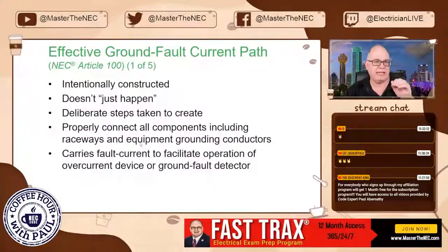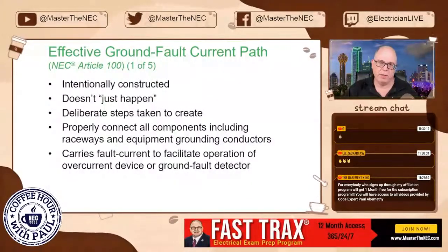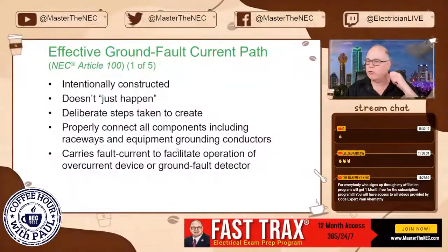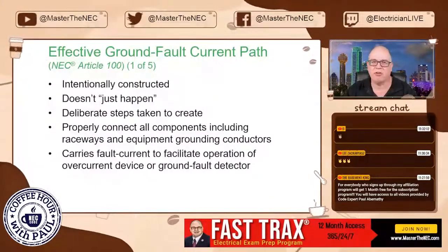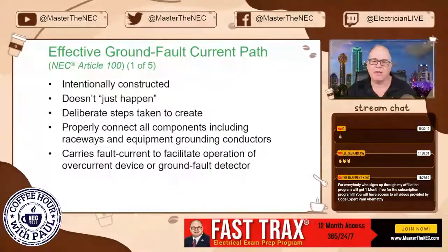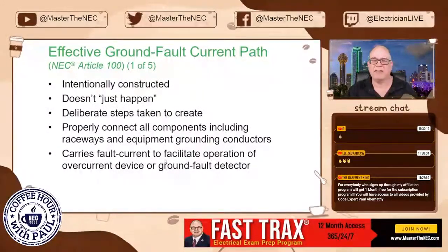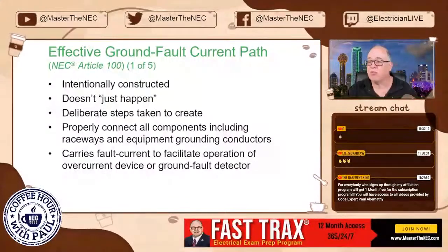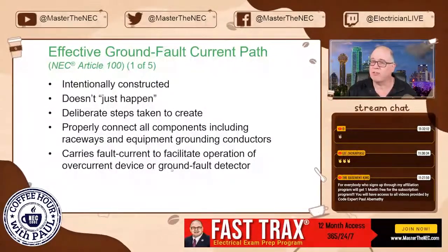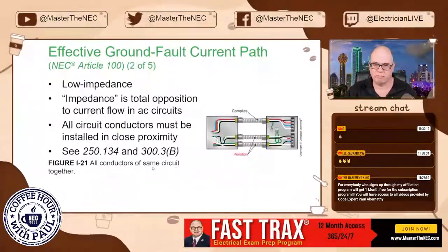You need to habitually train your folks on that. Properly connect all those components, whether it's the raceway, the fittings, the terminations, connection to cabinets, all of that. It carries fault current, again, to facilitate the operation of the overcurrent device, as well as, in some cases, for ungrounded systems, ground fault detectors, okay?